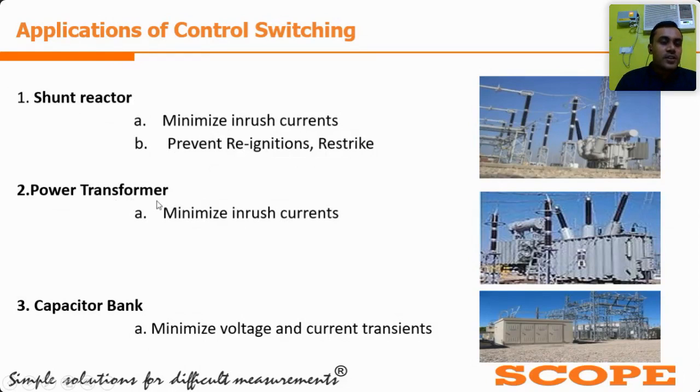In the power transformer, at the time of re-energization, some inrush current arises in the ICT core that may be up to 2 to 3 pu. Pu, I mean, it may reach 2 to 3 times the full load current.